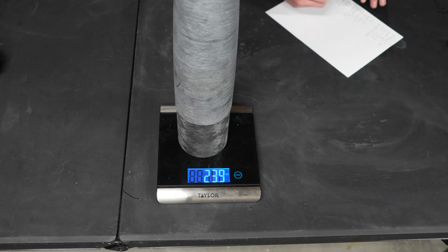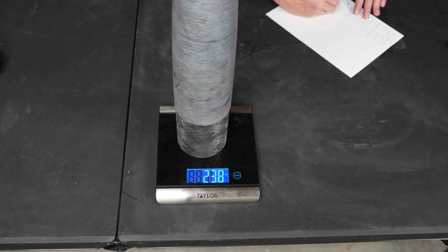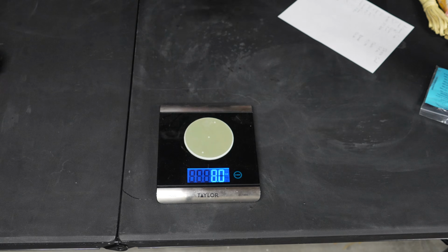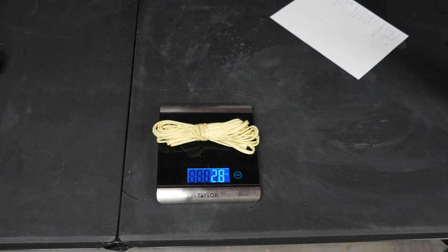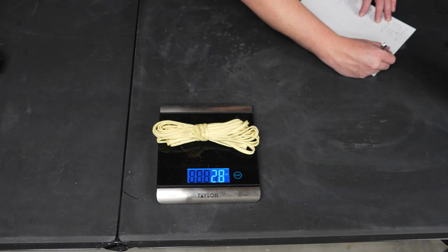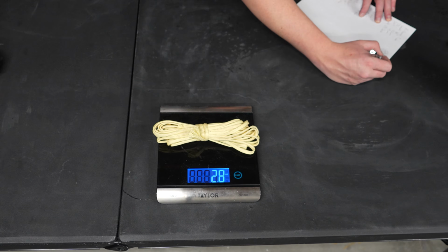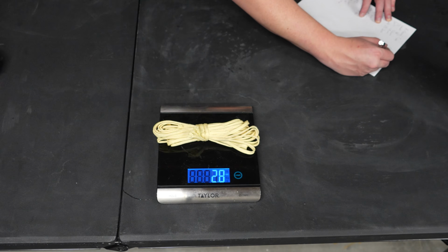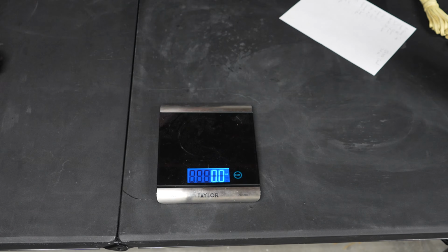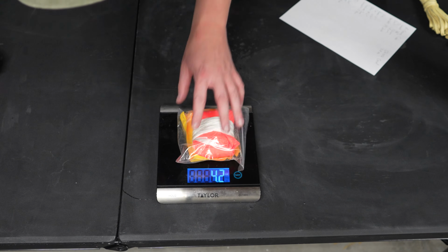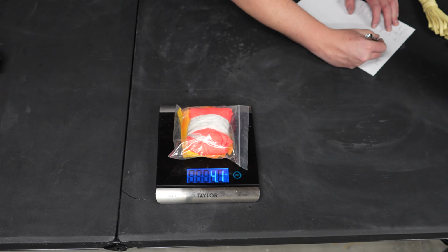While the scale's out, we're going to go ahead and move on to weighing some odds and ends like our bulk plates, our vent band, shock cord, parachute, and even the Nomex protector. If you already have hardware like quick links and eye bolts for your recovery system on hand, weigh those too. Remember, we want everything to be as accurate as possible if we want accurate simulations.